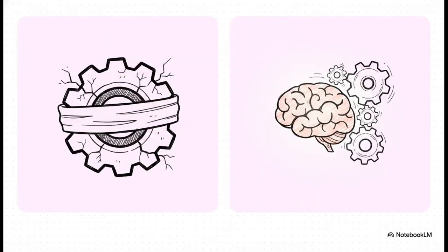Right, so why are we facing these massive numbers? Well, it really comes down to the control layer. Traditional automation relies almost entirely on rigid programmable logic controllers, or PLCs. These legacy systems are built to execute static rules exactly as they're programmed, over and over again. The problem? They are completely blind to physical wear and environmental drift. If your facility's temperature fluctuates even a bit, or a machine component starts vibrating slightly out of spec, that static PLC is totally oblivious. It just happily runs the program until the machine literally breaks.